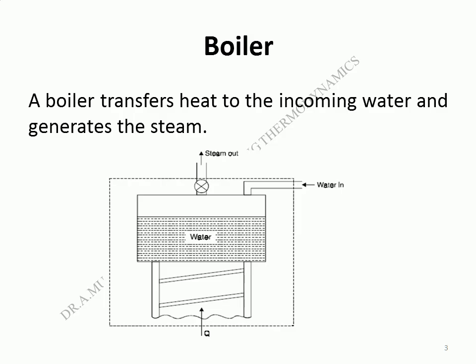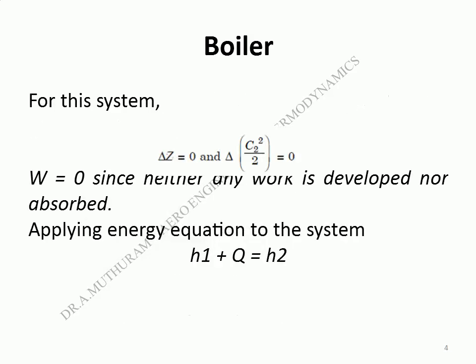Boiler. The boiler transfers heat to the incoming water and generates the steam. For this system, change in potential and kinetic energy are 0 and work is also equal to 0 since neither any work is developed nor absorbed. Applying energy equation to the system, H1 plus Q equals H2.